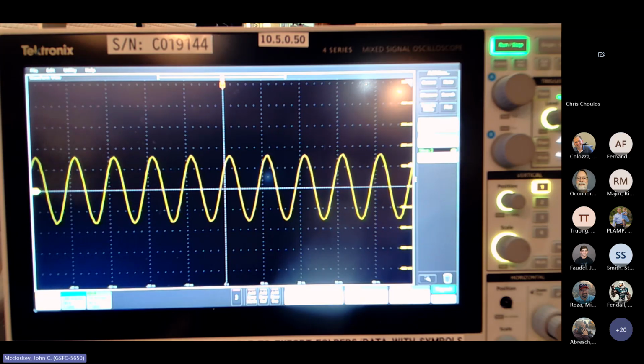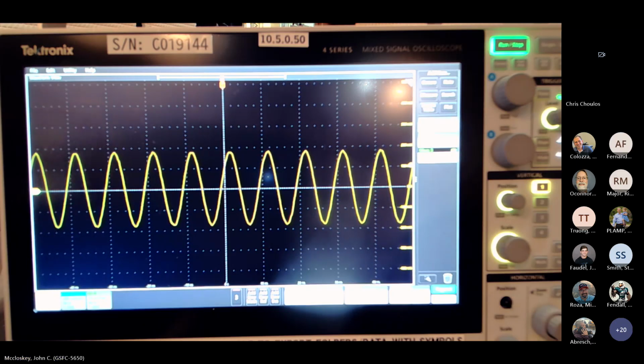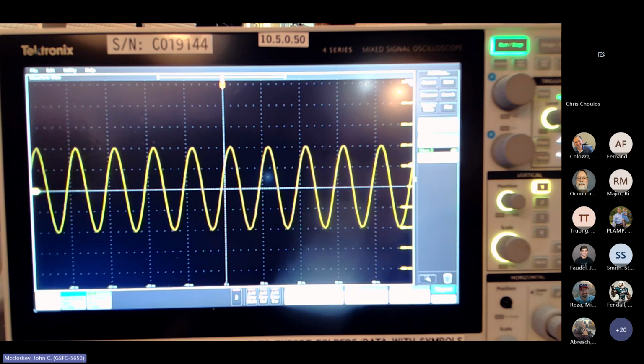Okay, so I'll bump up our signal level by another dB, so to 109. Now that's reading 125 millivolts RMS. So it's still a little low. We'll go up to 110. And that's reading 140. That's a little bit low.